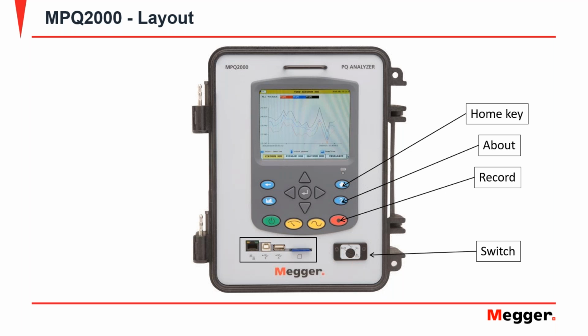There's a switch here which has two positions: aux and VA. In the aux position, the unit relies on an external source of power, so you would need to connect the power cord to the recorder and connect it to a power outlet. Typically, when you take this unit out in the field, you leave the switch on the VA position, which means it's going to rely on the voltage that's coming in on the VA channel.